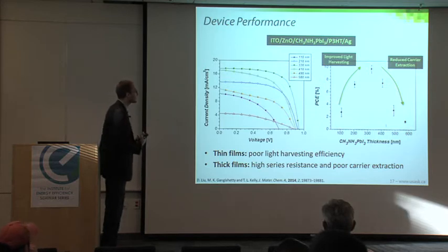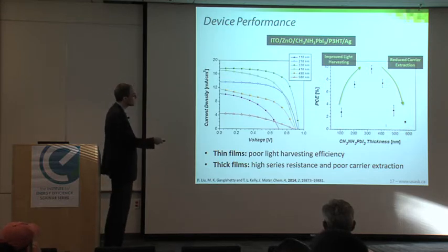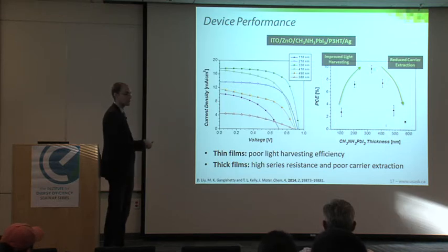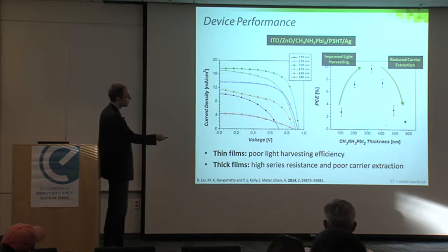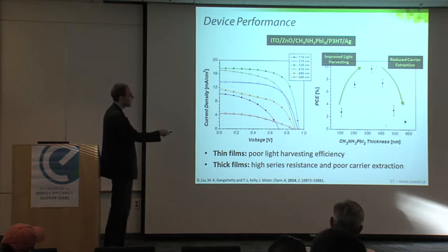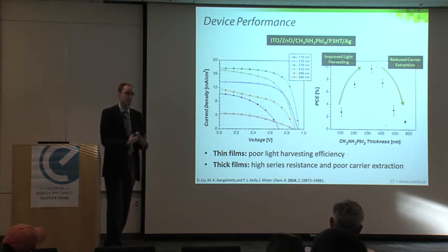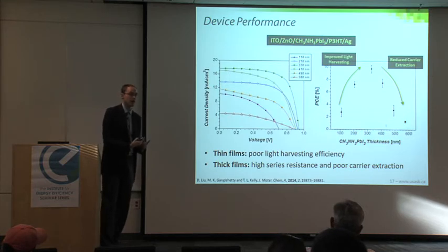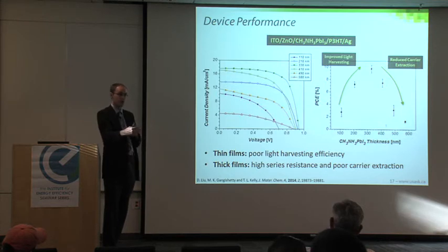And so what we found was that as you increase the perovskite thickness, initially you see a dramatic increase in current, and that's simply a consequence of Beer's law. So you're absorbing more photons, more electrons, more current. But the problem is once you get past this 330 nanometer sweet spot, the efficiency tanks. It plummets because you've really, at this point, exceeded the charge carrier diffusion length. And so the electrons and the holes simply have too far to go before they can reach the electrodes.